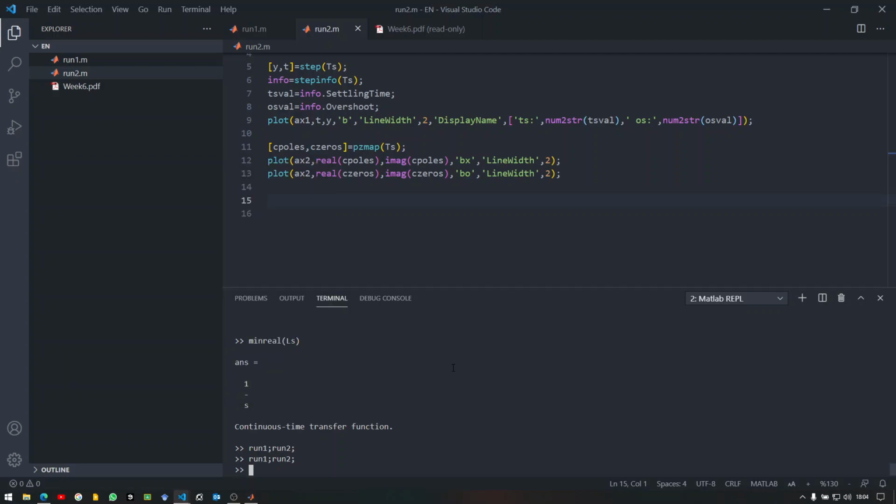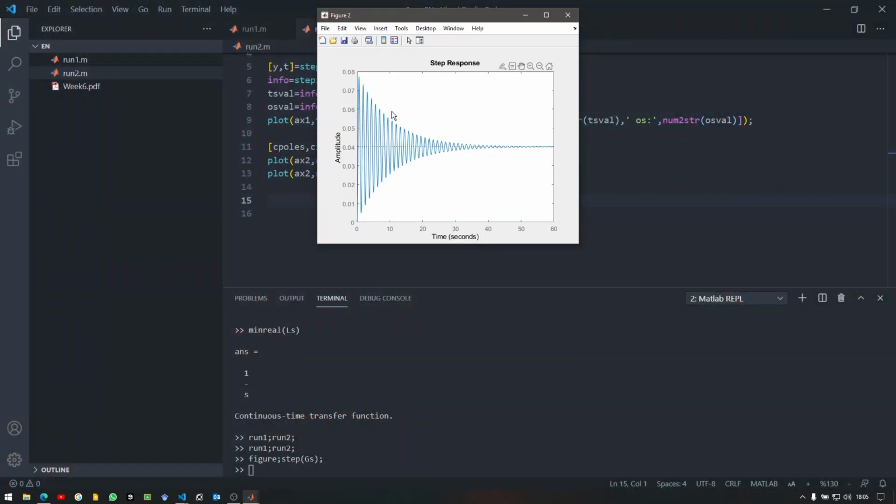Now, we didn't look at the system's behavior, but if you look at the step response of the open loop system here, what you can see is we have high frequency oscillations here, and I can immediately see that my damping ratio is close to 0 because I'm close to the marginal stability here.